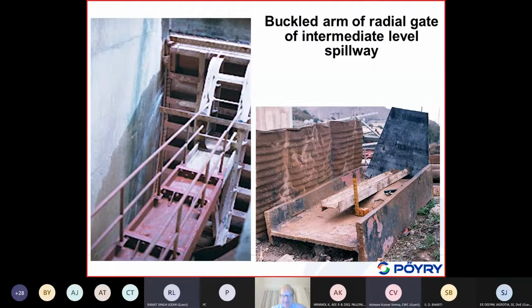It is clear that if this arm is deforming, most likely you will not be able to operate the spillway. Now, these high axial forces, which caused this local buckling, were basically due to the hydrodynamic pressures. Some people have problems with hydrodynamic pressures or claim they may not exist or have not shown damage due to that.